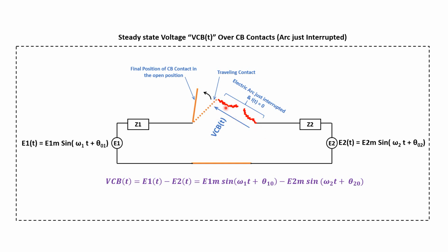Otherwise, if this voltage is higher than the rating value and the current is high, then because the arc has not been cooled down, there is still a chance of re-striking and reconnecting the circuit to each other, which is not good when breaking overvoltages. The overvoltages cannot be studied by this simple RL circuit. But generally, we know that we shouldn't have re-striking, and the standard puts some criteria to minimize this incident.